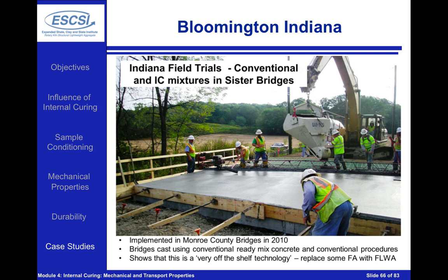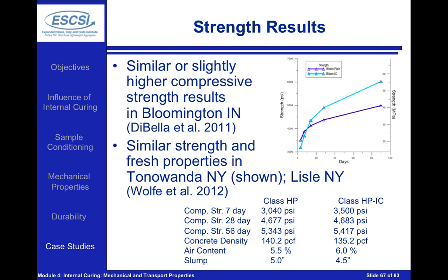I will mention that there are no pumping concerns we've had on projects since then, and in fact we pump the concrete and don't have any additional problems with pumping the internally cured concrete because most of those, we have a high degree of saturation in the pores, so we really are seeing that the internal curing is not really affecting the pumpability of the concrete at all, and we place it with pumps now on a consistent basis. Here we can see some of the results from those Bloomington projects.